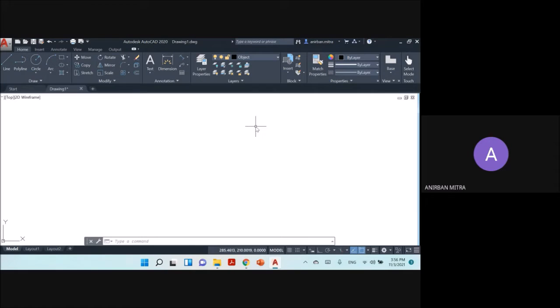So it has to be put within a margin which needs to be referenced, and there should be some grids present. There should be a title block which gives us relevant information about that object being drawn, and also who is drawing that object, for what purpose it is being drawn. So all this information would then be supplied in the form of a paper space.